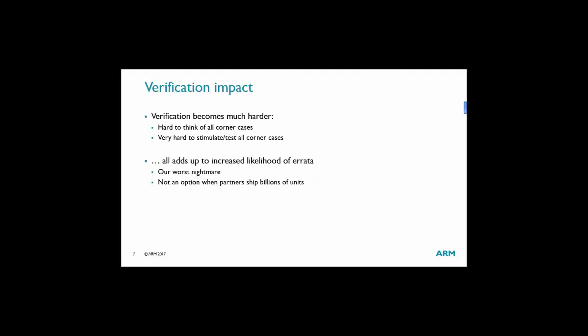So at this point, we're at a formal verification conference, so you'll expect me to say that formal kind of rushes in and solves everything. The breadth-first search nature of bounded model checking will, of course, find the corner cases. You don't need to write your stimulus ahead of time. Of course, the tool will consider for you all these different possible horrible forwarding paths and speculative views of state within the processor. But the problem is that without suitable properties as checkers for the tool to work with, it's more or less useless. You can't actually verify anything unless you have the checker.